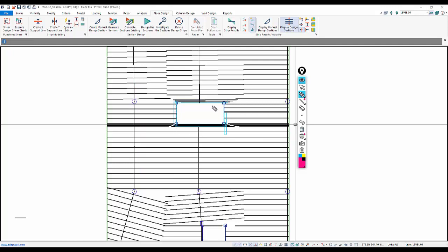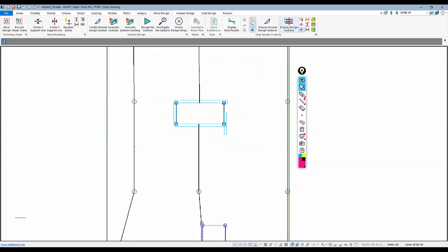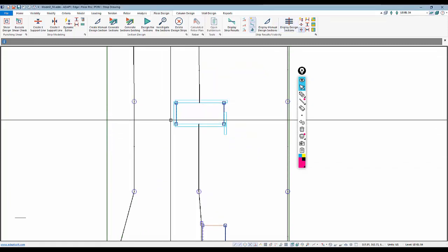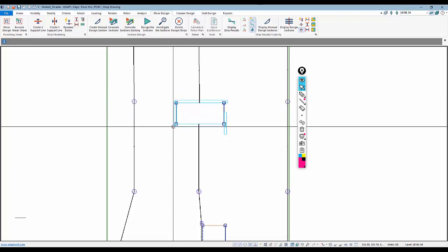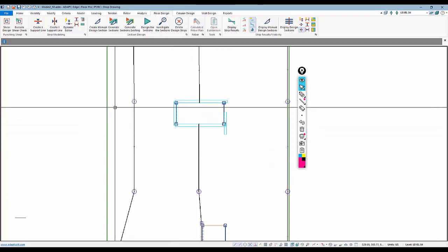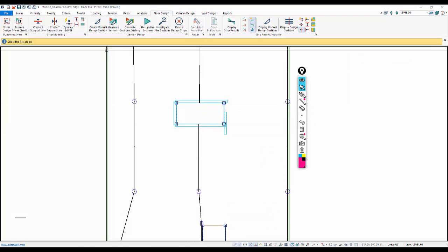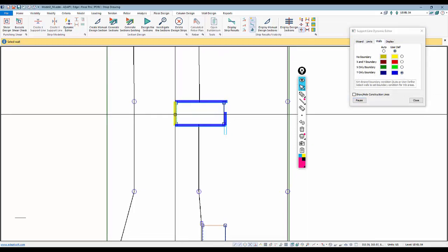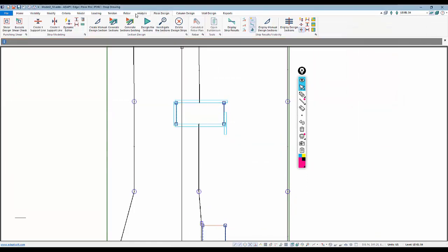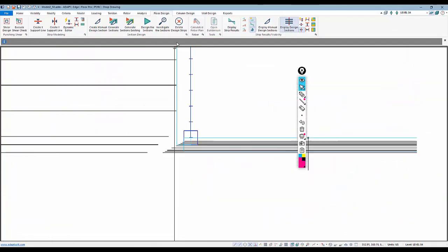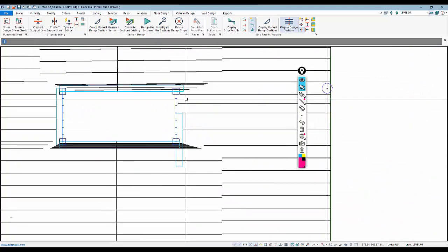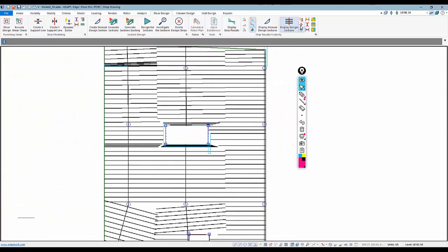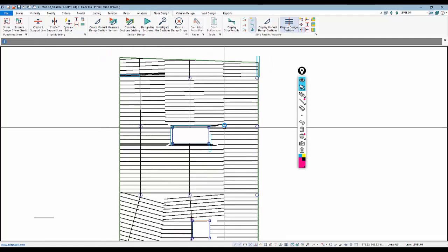And also we wouldn't show the stress for the flexural stresses, compression or tension for the cuts that extend over a wall. So one nice thing with this version of the program is we can tell the program to ignore or apply the boundary condition for these walls relative to the Y or the X direction. And I'll go back to Dynamic Editor under Walls, and I'm going to say User Defined. I want this to be a Y boundary only, and I'll select that wall and that wall. I'll close that. If I regenerate the strips now, you can see that these cuts extend just off the face of the wall. And that's one way to use those boundary conditions set in that dialog under Dynamic Editor for strip modeling.